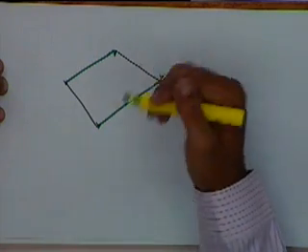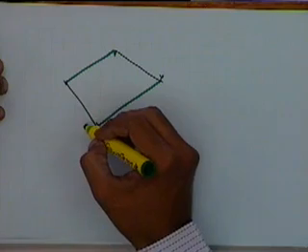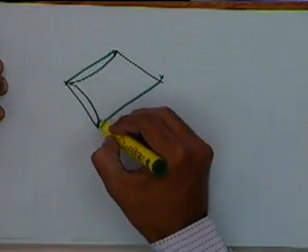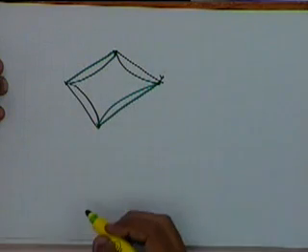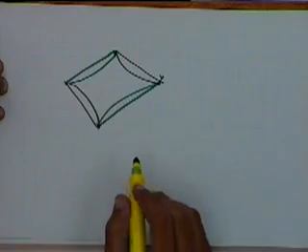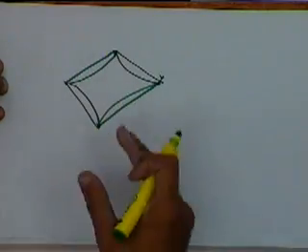Okay, similarly my stress and strain patterns will also be equally restricted. I am doing linear interpolation everywhere. So for 4 noded elements I have to have straight edges, but for an 8 noded element I can have curves like this, and so on. Extra nodes on the same element will give you more flexibility in defining the element.